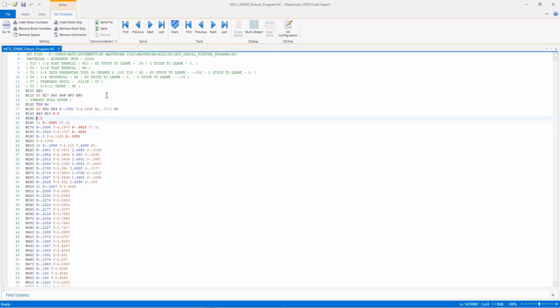As we go down a bit further, we'll start to notice that other things are color-coded. The Z coordinates are in bold red, and you'll notice that we have positive and negative values. Our X's are highlighted in blue, the Y's are in brown, and we actually have our G values, G1, G2, and so on, in a lighter green than we see in our comments. We also have other things color-coded like this A0 because our post-processor in this case actually had a fourth axis. So it's telling us that the A value is 0, and it tells us that we have our M code as well as our spindle speed, and all the other different things that we would need to find in our code quickly are all color-coded for us.